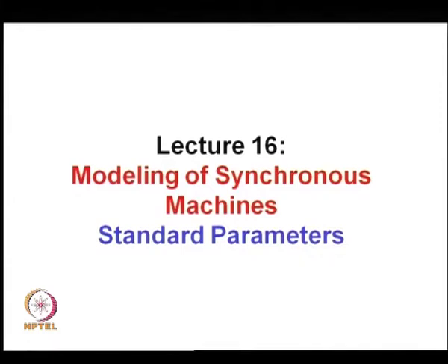Now, suppose I have got the synchronous machine equations, the d q 0 flux differential equations, then the f, g, h and k flux equations, the differential equations, and there is a linear algebraic relationship between the fluxes and the currents. So, my equations in fact constitute a combination of differential and algebraic equations.